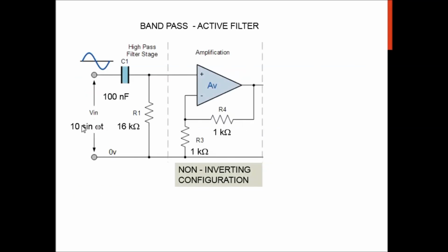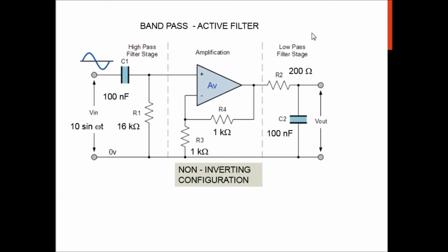So what if we have designed the high pass filter as follows, where your resistor here is the same, right, for the gain of 2 just now. So we want to make it a band pass filter this time. So what you need to do is just connect it with a low pass filter. And based on these values, you can get the values of the low and high frequencies. Can you calculate those values? It's very easy because this is the FL and this is the FH. So I think I leave it to you to calculate those frequencies.